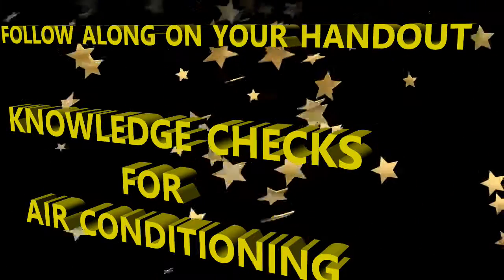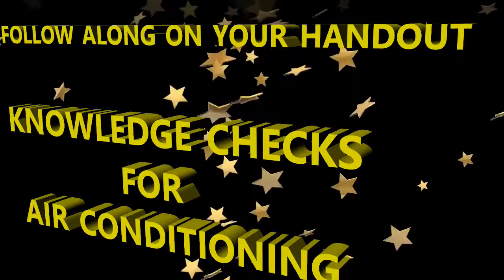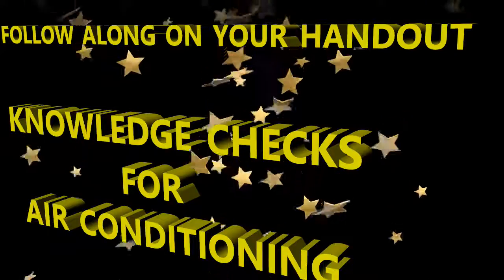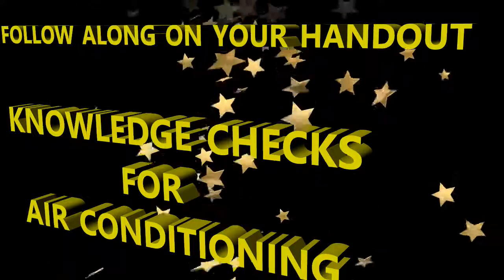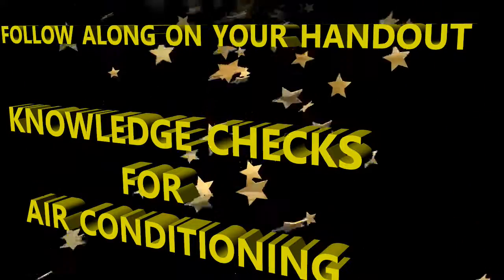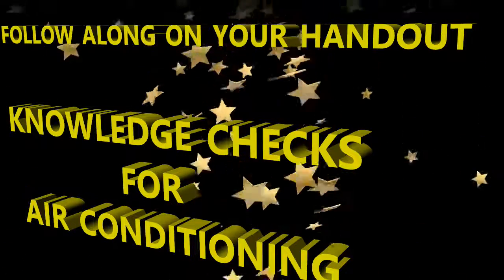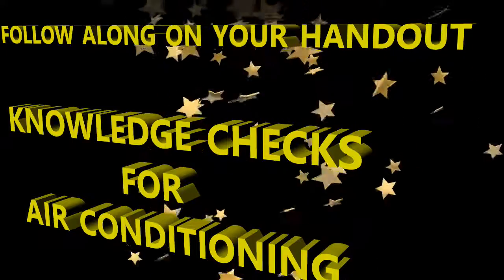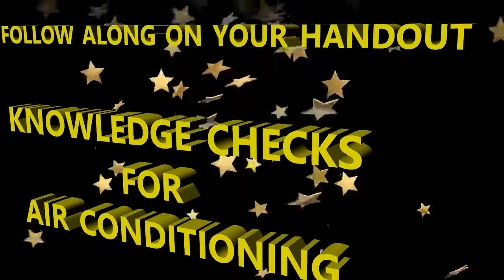Number 3. The ECAM system bleed page shows pack indications and faults. Is that true or false? That's actually true. Number 4, I didn't mention the temperature ranges, but I'm going to go ahead and give you the answer now. The range of temperatures on the selector for the zones is going to be 64.4 degrees Fahrenheit to 86 degrees Fahrenheit. So that's your range from cold to hot, 64.4 degrees Fahrenheit all the way up to 86 degrees Fahrenheit. Number 5, how many air conditioning packs are there? 2 or 3?